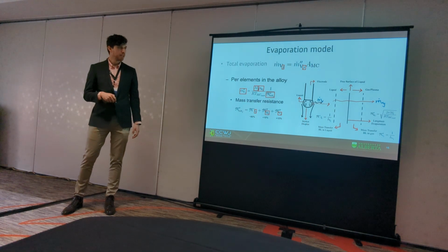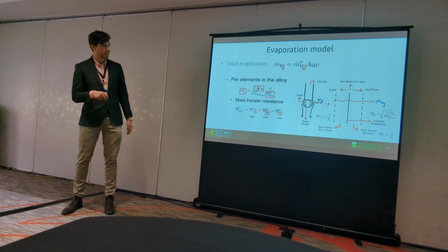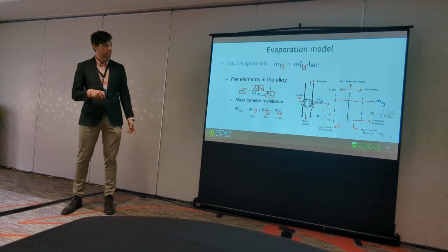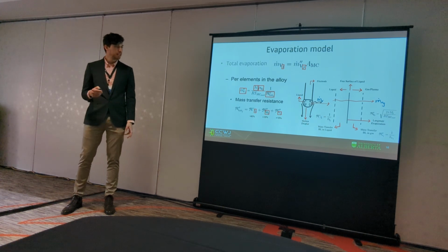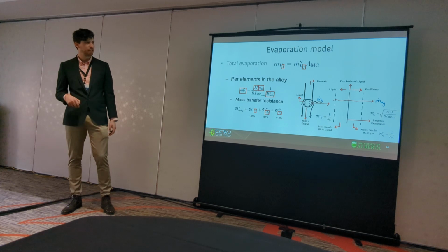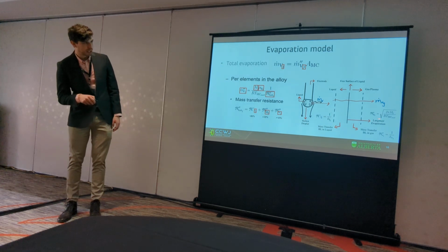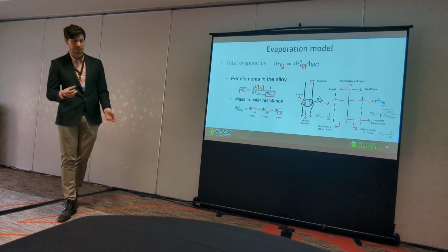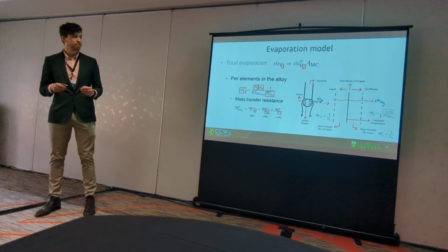So if we want to control things, maybe it's here where we can increase. In the vapor we cannot do much, but in this boundary layer, maybe we can increase it or decrease it, and we're going to have different effects. So if we look here, we have the droplet temperature, and this is the resistance of the liquid in this boundary layer.